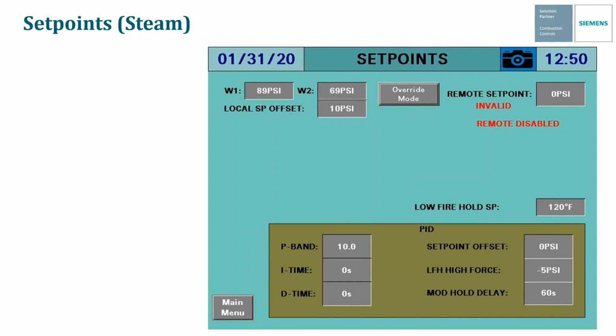So to go over the basics here on the Setpoint screen, we see here we have a W1 and a W2 set point. Now, these aren't just simple set points. It's actually two separate programs. And in later slides, you'll see how we adjust the programs for each one of these based on how the boiler's lead rotates and also how the lag system is set up.